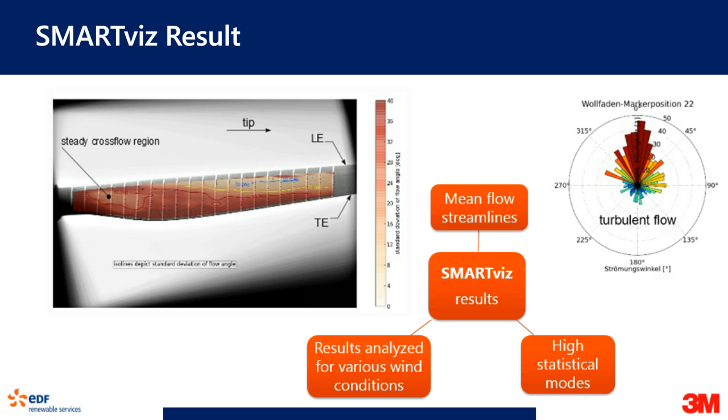The output can help us understand where the flow separation is actually happening and what the best method is to address it. But again, with respect to different wind speeds and wind directions, your flow separation can change. So we need to optimize where to install so that you get the most out of your vortex generator installation. That can really help us to differentiate from an installation standpoint.